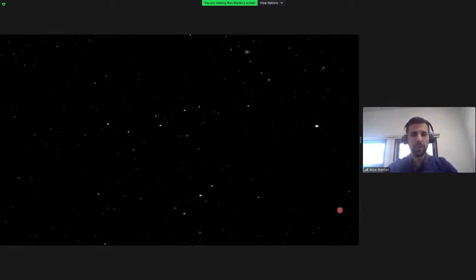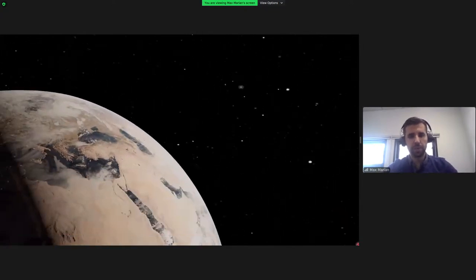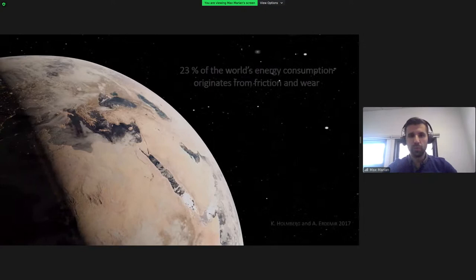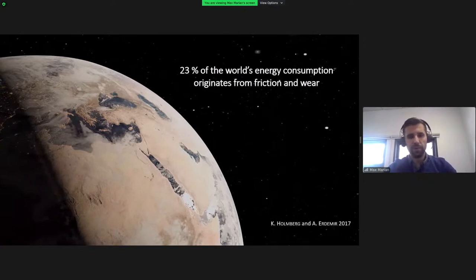But before we get into any details, let's start with the big picture, and why we would want to predict the behavior of the mentioned contact types. According to Holmberg and Erdemir, around 23% of the world's energy consumption originates from tribological contacts, and about 20% of that is used to overcome friction, and 3% is used to remanufacture or replace worn parts due to wear and wear-related failures. So to get a better idea of what these 23% mean, let me express it in an energetic way. This corresponds to annual losses of 119 exajoule per year.